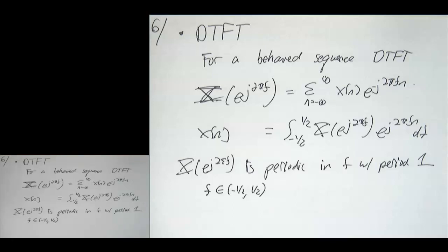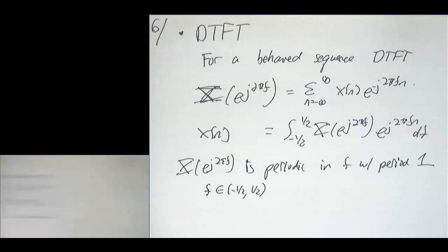So the transforms are good for intuition. They're also really good for debugging. If something's not working right, what happened to the received spectrum? Is it shifted? Is it scaled? That can give you some clues about how your software is misconfigured or how your hardware is having problems. Okay, so that's Fourier transforms.